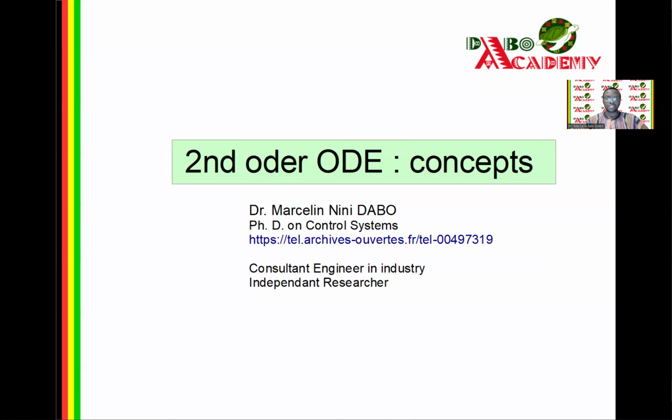For second order systems, I have started presenting the fact that it is possible to compute the time response of any given second order system. Okay. Might they have the damping ratio that is less than 1, that is equal to 1, or greater than 1, meaning that respectively, when they have an underdamped, critically damped, or overdamped system.